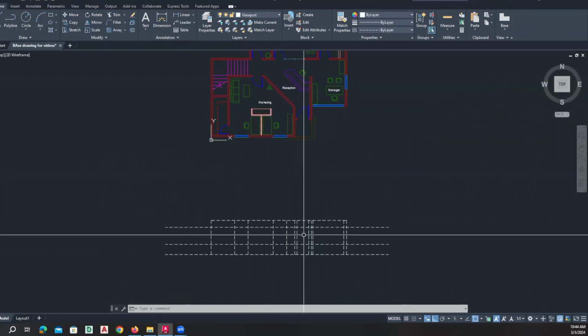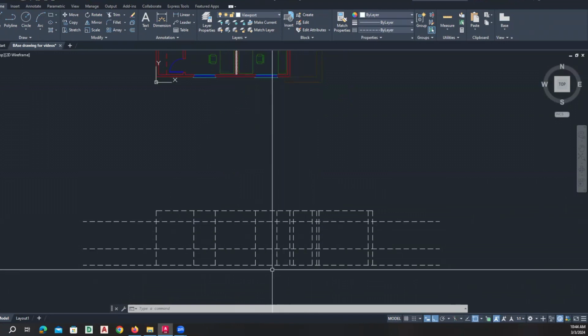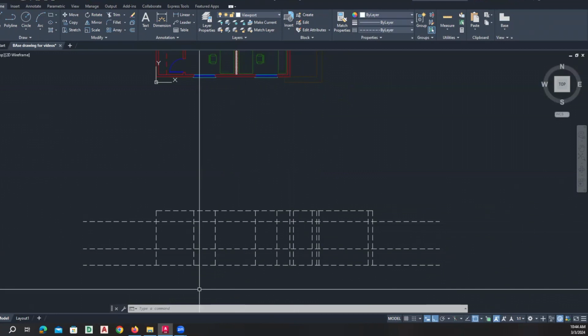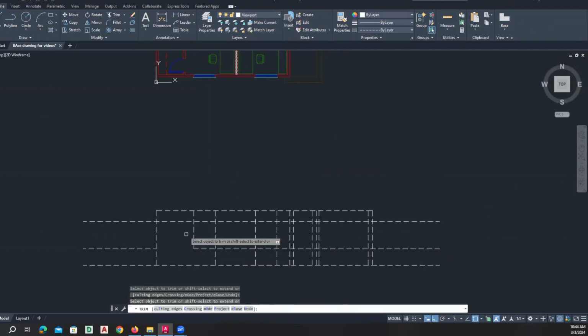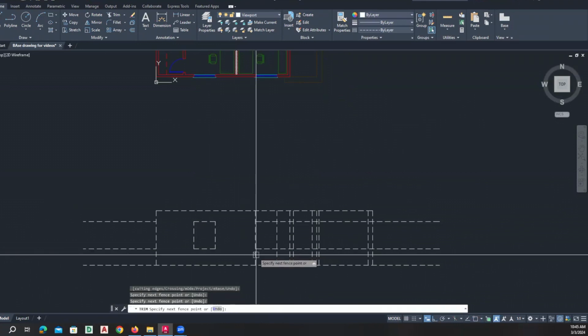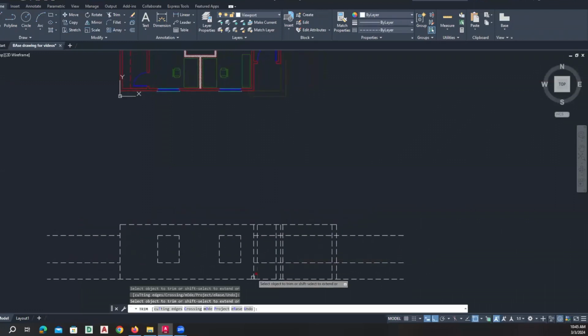And my door, let's say my door height is at the top of the window. So that's 3 and that's 8 feet, right? So now I can start to trim some of this information so that I can clean up the drawing and get a sense of what it is I'm actually looking at. So these are windows, so I will trim around those. Right. This line here represents the corner, so that does not get trimmed because that will go completely vertical from the ground plane up to the roof.